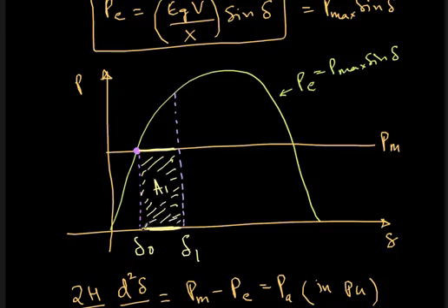So this is accelerating energy. The rotor is accelerating. That's why I am increasing from delta 0 to delta 1. And at this point, since I am in acceleration, I am rotating at a super synchronous speed. So even though the fault is cleared, the delta angle will keep increasing, and it will reach a point which is delta max. But then at delta 1 itself, the electrical power is going to come back because the fault has been cleared. So at this point, electrical power is greater than mechanical power. For example, you see here electric power is here, mechanical power is only this much.